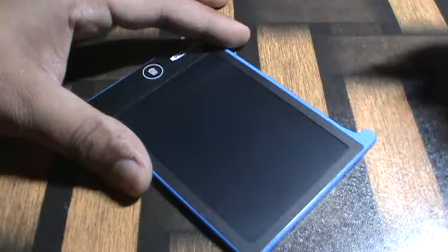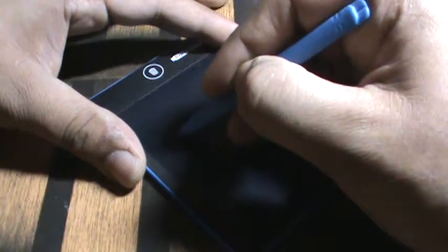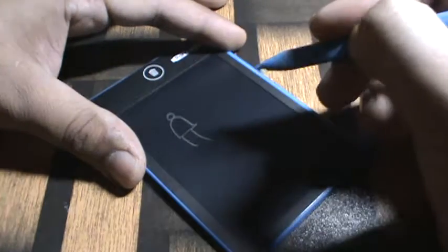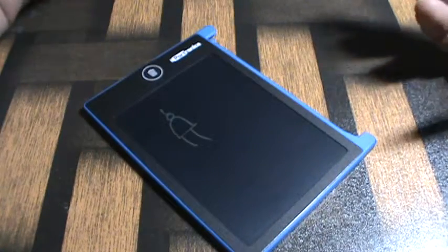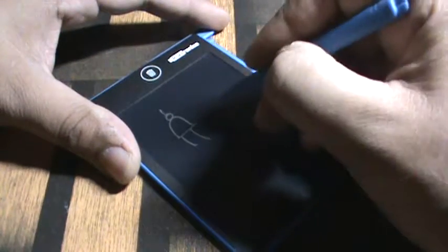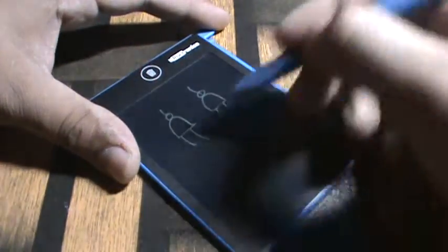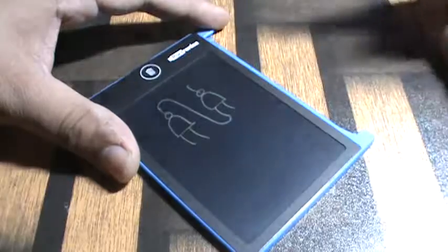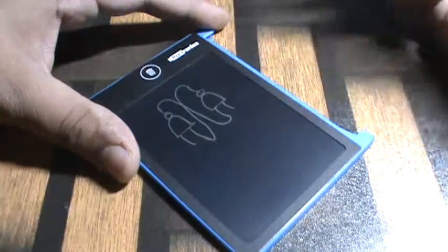So a register looks something like a NAND gate or a NOR gate. I'm using a NAND gate. A NAND gate looks something like this, I hope so. When we create a circuit similar to this, we take two NAND gates, and the output of one NAND gate we connect to the input of the other NAND gate, and the output of the second NAND gate we connect to the input of the first NAND gate.